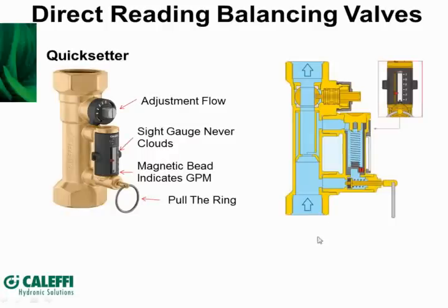And if you look at a cross-section of this, here's what you get. Here is that little bypass loop here. Normally no flow is going through here, but when the contractor pulls this pin, it induces a flow by way of a Venturi right here through this bypass loop. And this is a magnetic disc right here attached to a spring. And that disc here in red is attracted to that ferrous bead. Okay? And it's calibrated in such a way that when you look at it straight on, that bead rides up to indicate in gallons per minute the flow rate.